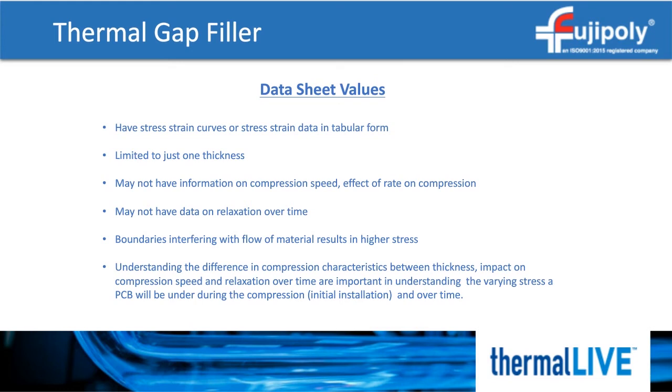You want to have a good understanding of how thickness, compression speed, and relaxation over time play a part in the stress on the PCB, especially when you're looking at very sensitive devices. So let's look at some stress strain curves for some typical thermal gap filler materials.